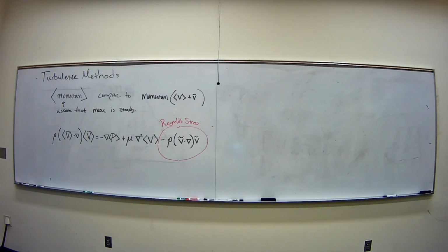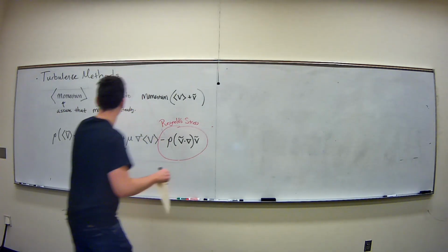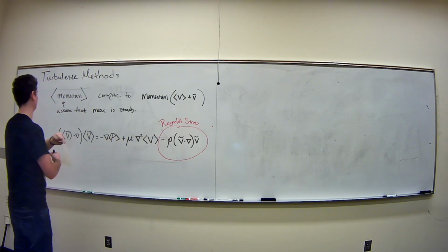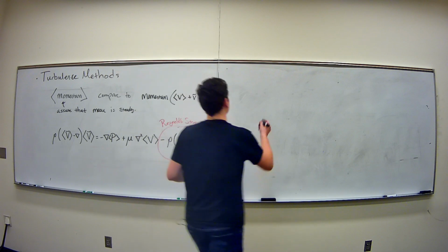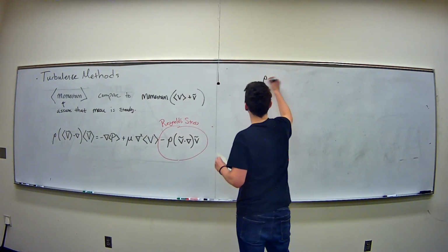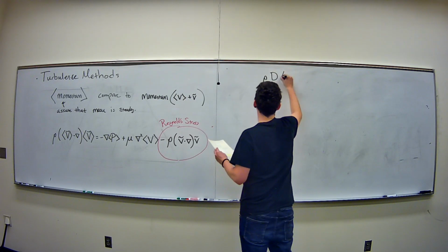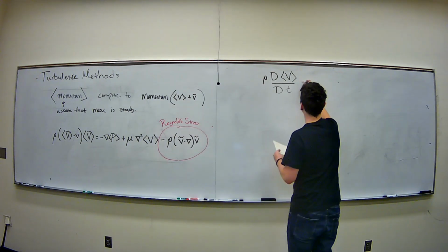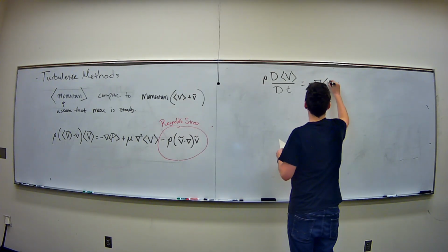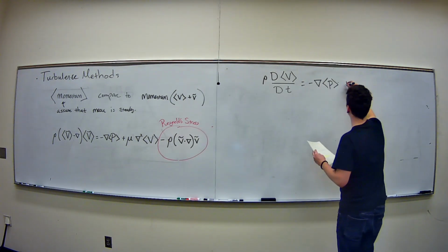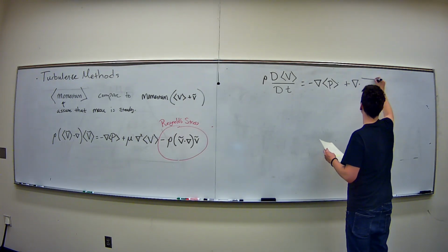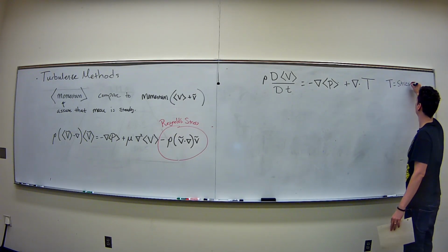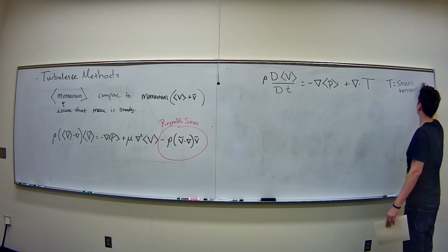Okay, so a better way to see this momentum equation, because these are all the terms put out there, is if we do the divergence of the stress tensor like we did before. Keep in mind, everything's incompressible right now. We can even do this not at steady state, where I have my material derivative, an average pressure field, and this divergence of the stress tensor. Okay, this is the stress tensor.